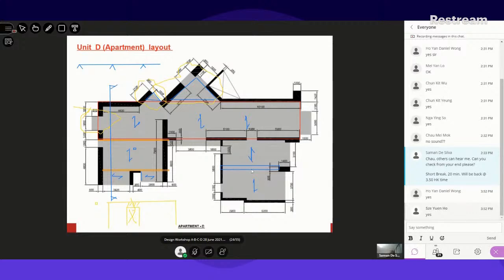This is the low part. I'm looking from 1, 2, 3, and a bit. That part is actually spanning in and out of the page. It is not even like a cantilever. Okay, so the direction of reinforcement is the other way around. So it is spanning between that and that.